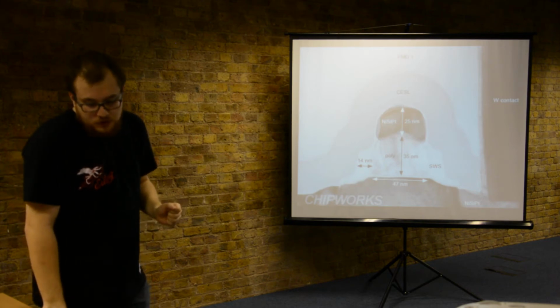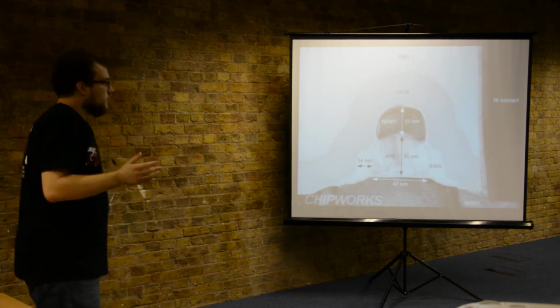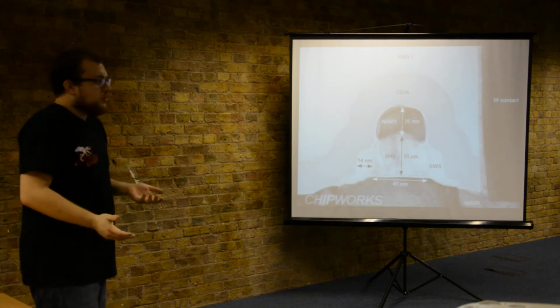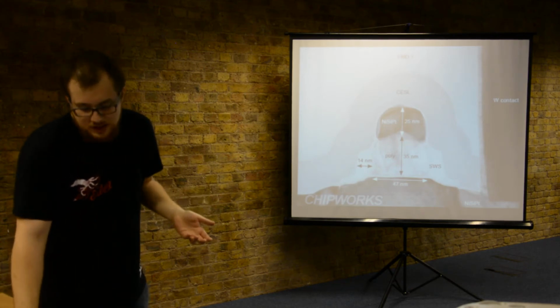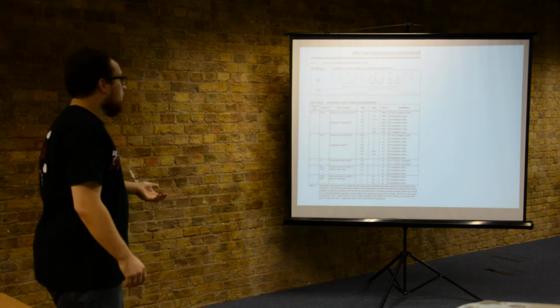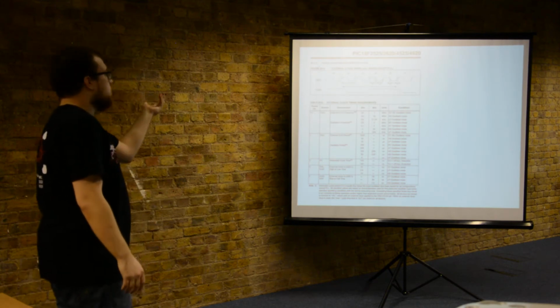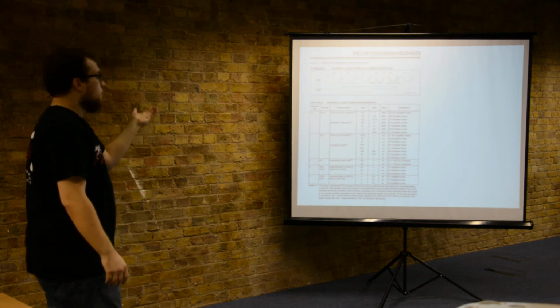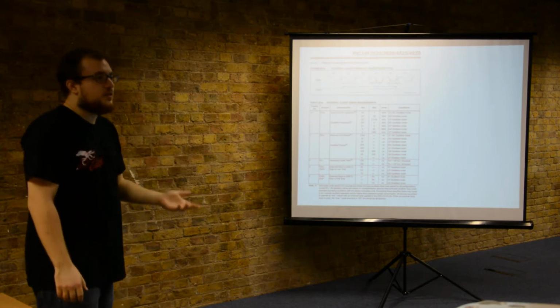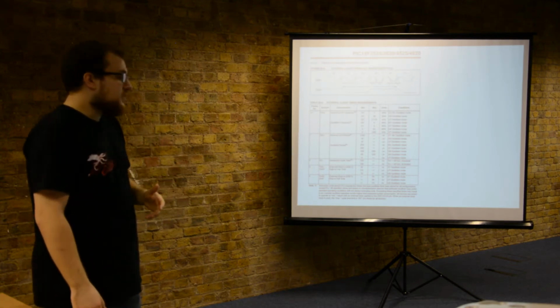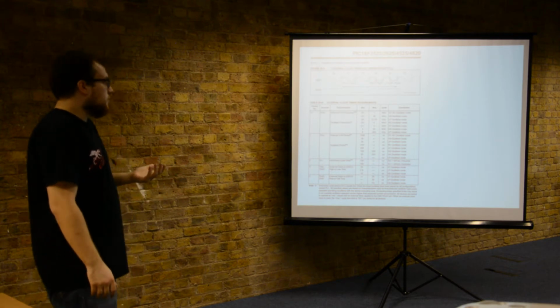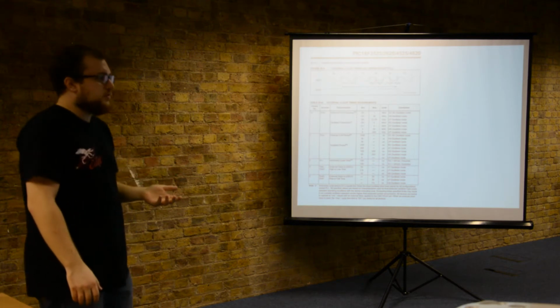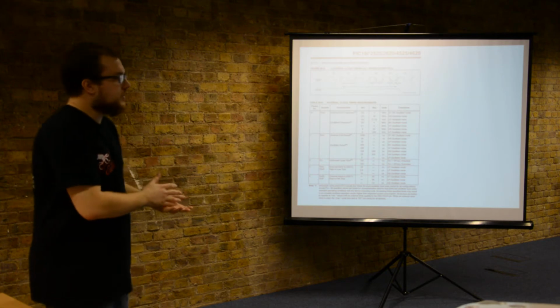But most commercial microcontrollers that you buy don't really bother with speed grades that much. They just say, here's a table, the maximum external clock frequency that you can run is 20 megahertz or something along those lines. What this means is that you can actually squeeze quite a bit more out of these devices most of the time by pushing them into